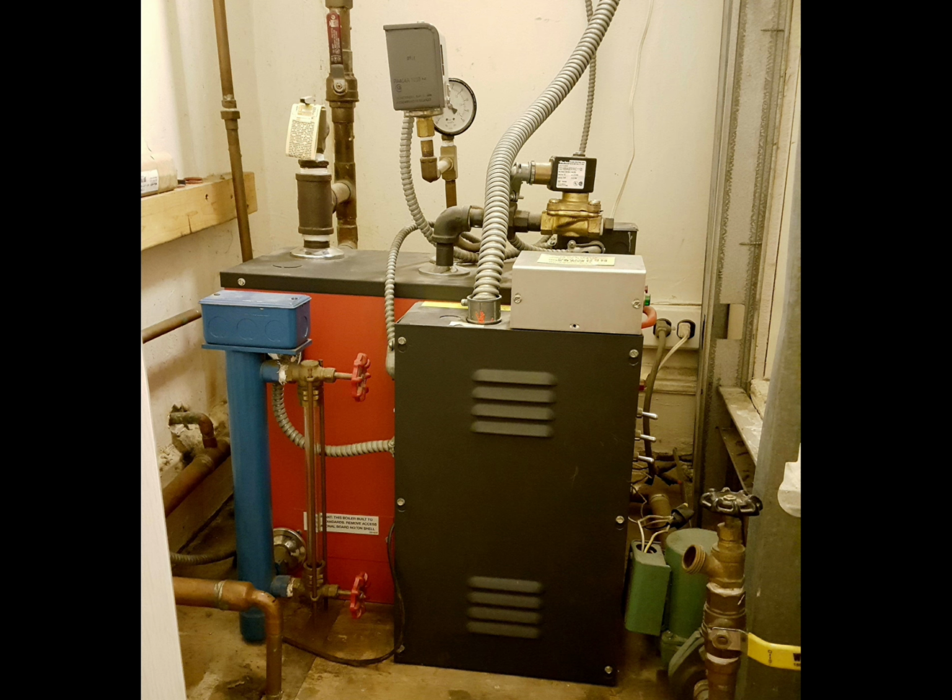And I'm bringing this up for a reason. The operating pressures of most steam systems don't usually go any higher than 5 to 7 psi, and that's commercial buildings. Private residential houses is typically about 2 to 3 psi, or in certain cases less. This one I ran here at 8 psi.